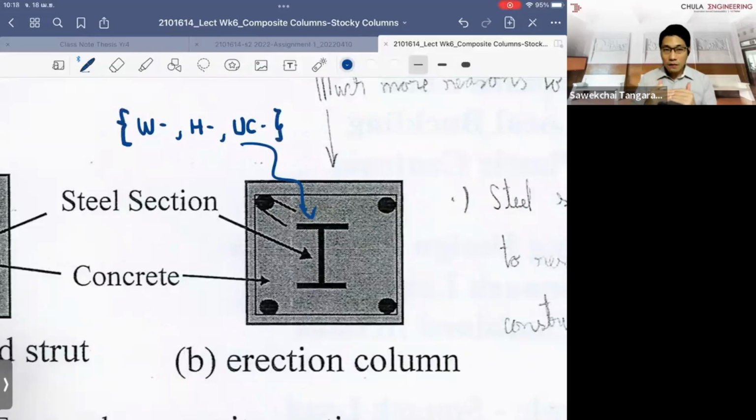The surface of the steel column is quite smooth. When the surface is smooth and you cast it with concrete, there can be slip between the steel column and the concrete itself. So in terms of research, they look at how they can provide friction between the steel member and the encased concrete.